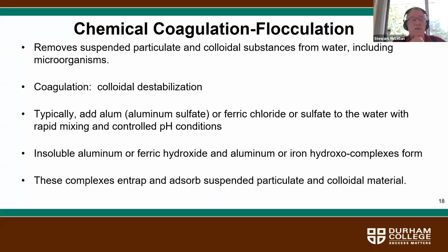And in those processes, we get things like chromium hydroxide, nickel hydroxide, copper hydroxide form, and those forms are insoluble and will settle out. These complexes entrap and absorb suspended particulate and colloidal material. And of course, once they're entrapped and absorbed, they're able to be removed through settling or filtration.